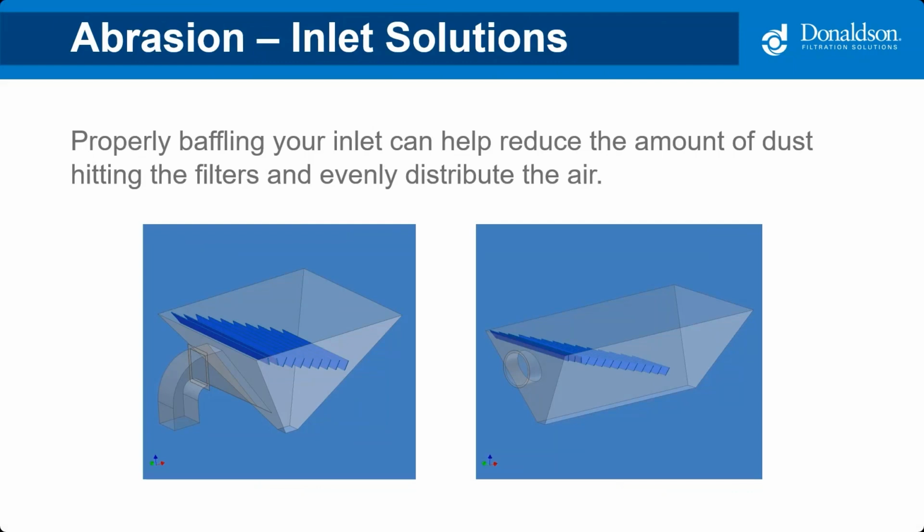And that's going to help to evenly, first off, it's going to help to knock the dust out. And then it's going to help to evenly distribute the air up into the dust collector. And this is definitely going to take care of the problem that I mentioned above. And then it's also going to really help distribute the air evenly and the dust evenly, so your filters are going to be able to share the burden and last a lot longer.